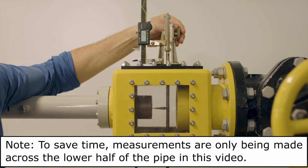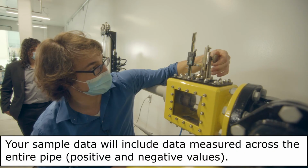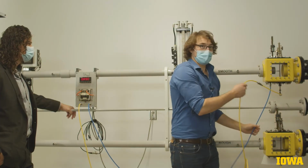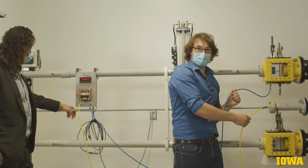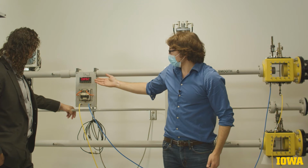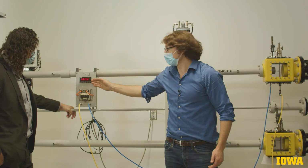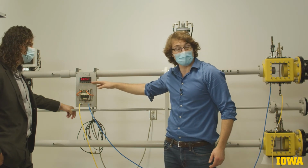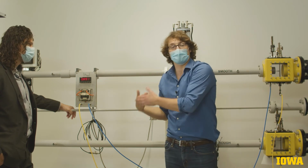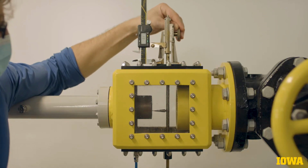So for the first measurement, we'll put this at 5 millimeters below the center line. And we have our high pressure leg connected to stagnation and our low pressure leg connected to static pressure, giving us a pressure difference of approximately 0.892 feet of water. Now you'll notice some fluctuation present in our measurement here. This is physical, and this is one of the reasons we take repeated measurements to quantify uncertainty. Moving to the next measurement location of 10 millimeters.